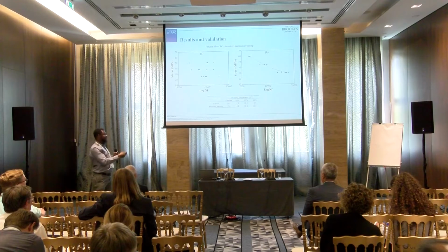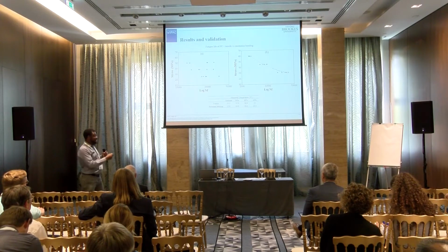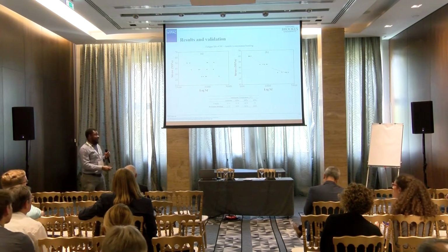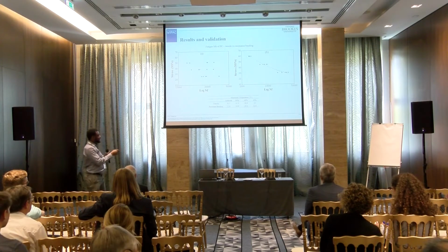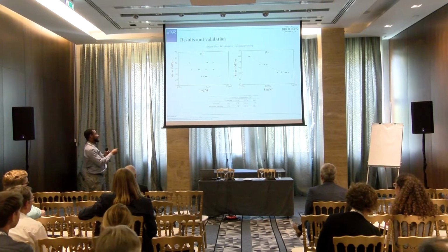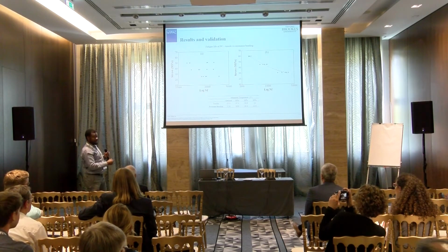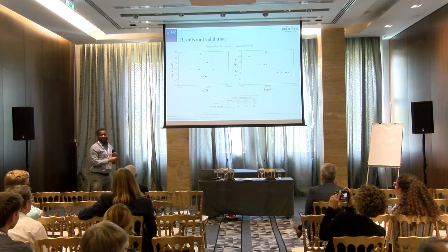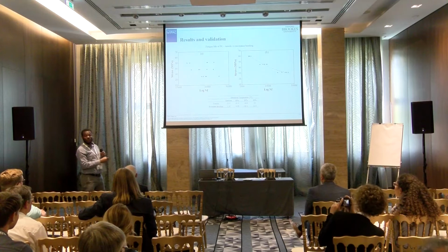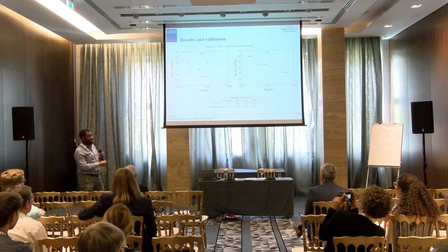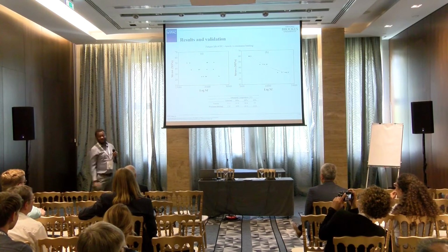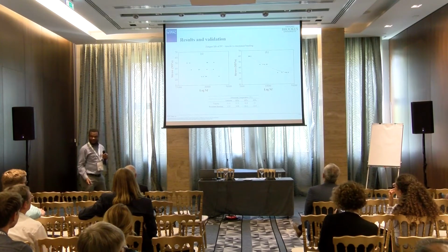And you can see a very nice curve. It's very, very simple to use as well. Within a day, you've done your work. But if I'm using the tensor test, trying to characterize this, using the bending or trying to reduce the frequency to be able to get this might take me the whole time of doing my PhD. It could take me 3 years trying to characterize only one SN curve, or a month, it could take a long time. But this will do it in a day or 2 days, you get your properties and then model your system. Very, very easy, very quick to use.